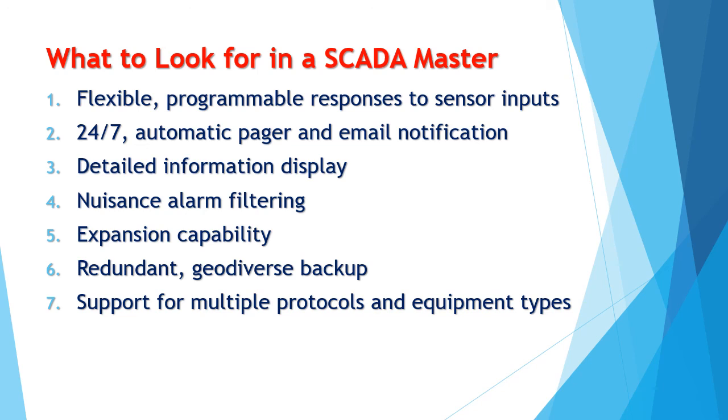And lastly, there should be support for multiple protocols and equipment types. Single vendor solutions aren't a great idea. Vendors sometimes drop support for their products or even just go out of business. Support for multiple open protocols safeguards your SCADA system against unplanned obsolescence.